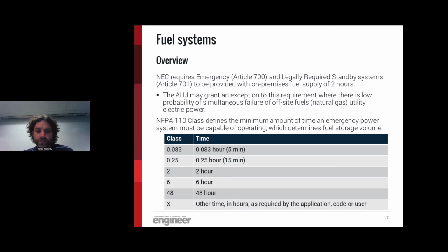Some of the other considerations for the fuel selection is what's available. Are you going to be allowed to put diesel on site? Does natural gas serve the area you're in? Or will propane be acceptable? And then the other component is what fuels are allowed. That usually gets into what are you trying to do with your engine generator? Are you just doing emergency power, or maybe are you doing some peak shaving? If you're doing peak shaving, then you also have to get into what the EPA or your local jurisdiction is going to allow as far as emissions.